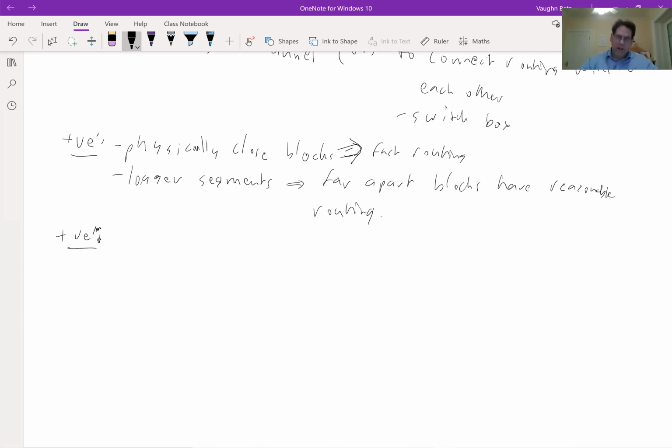This is probably a hard one to answer, but it turns out that island style FPGAs are also scalable. Hierarchical FPGAs benefit from locality, which is part of what makes them work reasonably well. But as you get to really big designs with resistive wires, they don't scale that well. Island style FPGAs are pretty scalable; they scale well to big designs.